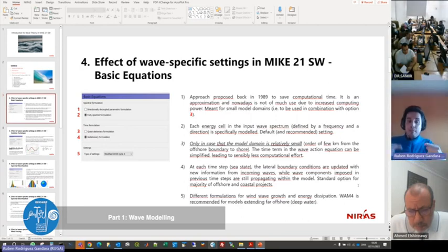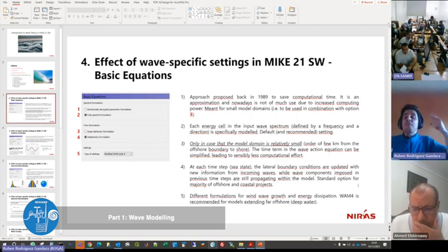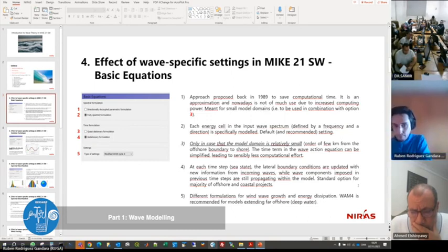So in the time that that wave took to go from the offshore boundary to the land, 3 different boundary conditions have happened at the boundary during that travel, which means that you cannot use, in that case, quasi-stationary formulation. You need to use non-stationary because, by the time that the previous waves are traveling, the boundary will be updated, and that will have an effect on the waves that are already in the domain.